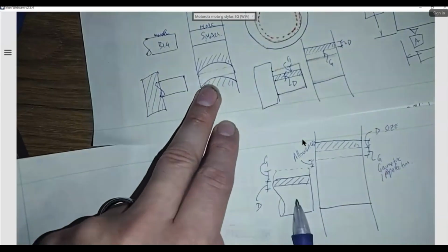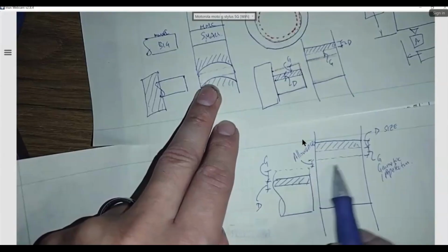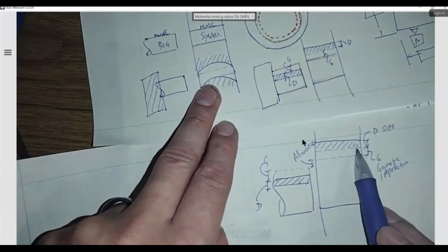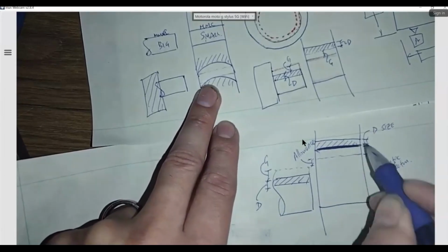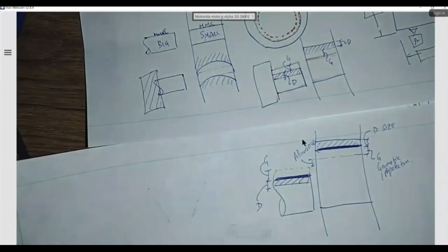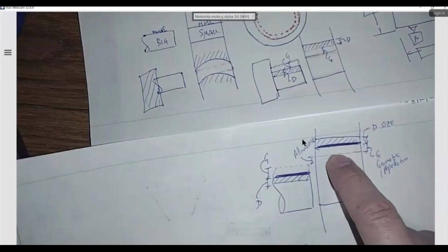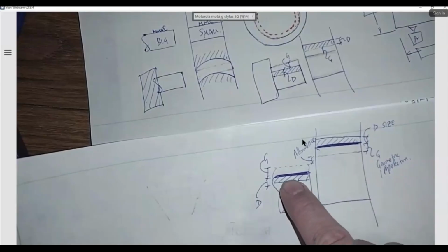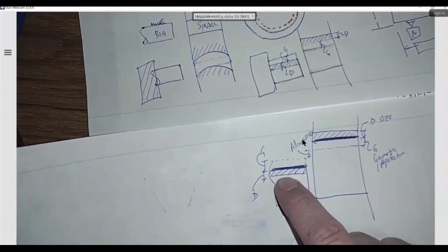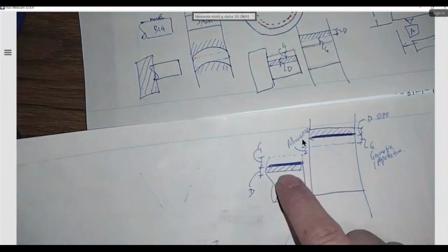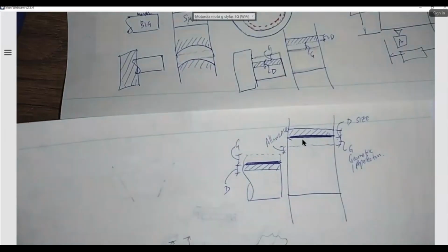And you guys will notice, even when my hole can be big, and it can have crookedness, and when my hole can be small, and can also have crookedness, at the MMC, when the hole is the smallest, or the shaft is the biggest, with crookedness, it will still fit. And if my shaft moves away from MMC, which is the biggest I can get, towards LMC, the smallest I can get, it will give me extra. You guys see it? Or am I going too crazy? See, I have better images. Let's see if I can show it to you.